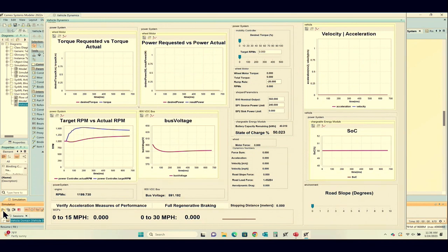quickly. So what you can do to mitigate that is use that PI control loop that then causes the actual RPMs to slowly come up to that target RPM. And that's what that activity diagram is doing. That was the purpose of that PI controller. So that was what we really wanted to happen there, and that's what's causing this to behave in an automatic way, is by using that activity diagram to say, at every time step, let's look at what the target is, and then slowly bring that up.